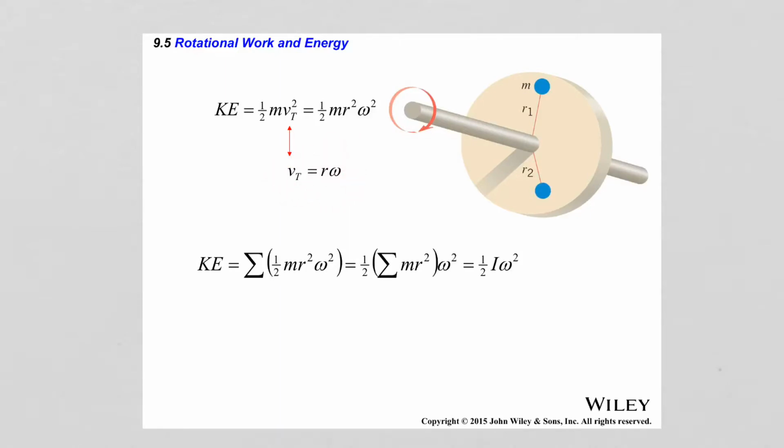So if I substitute in the kinetic energy expression, that gives me 1/2 m r squared omega squared. Then I can do the same procedure for all particles in the rigid body and add the results together. After regrouping as shown here, I get that the kinetic energy of rotation specifically is equal to 1/2 times the moment of inertia times the angular velocity to the second power.